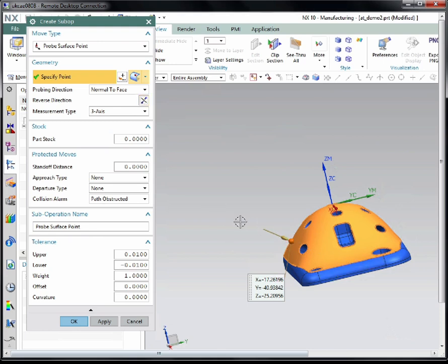You can give it an approach point, so approach clearance, and just give it a value. We'll do 6 to be safe. It's always good to give it a slightly bigger approach distance for a part alignment, in case it is unaligned, it might collide with the part. And you can also change your tolerances. Default is fine with me. Okay.